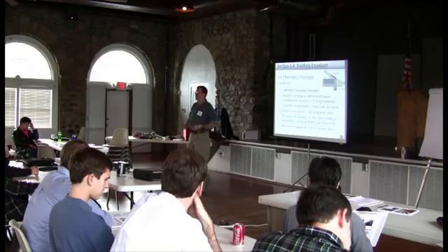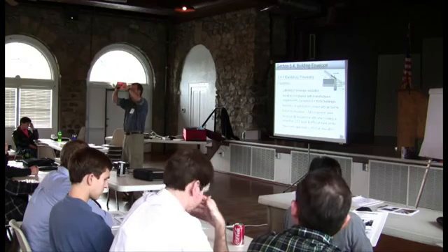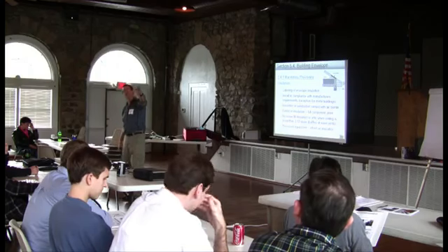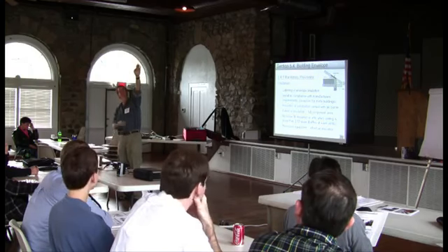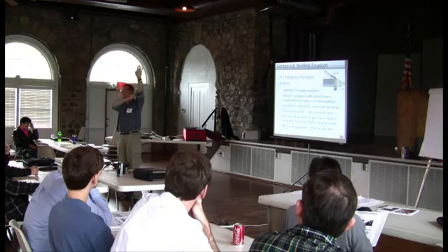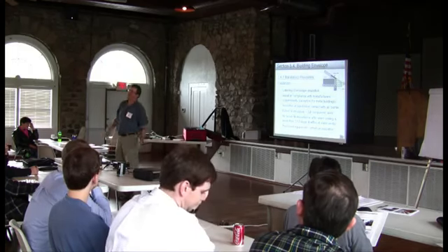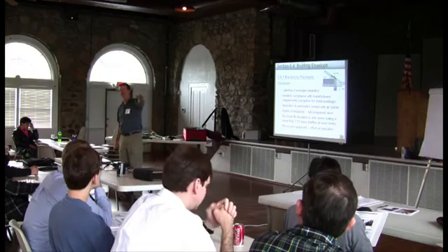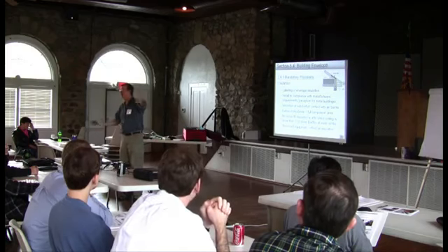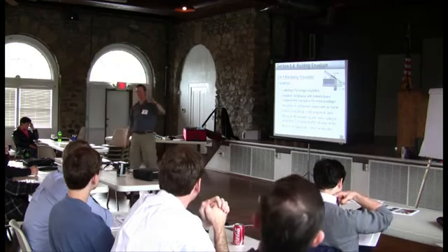Try to imagine someone has a scissor truss, okay, and there's an attic space up there, and let's say the truss is sloped like this in the inner chord here. Do you think that's a good candidate for blown insulation? What would happen if I tried to blow insulation right here? It would be kind of fun, right? So what they've said is you can only use loose fill if you're no more than a 3:12 slope. Kind of makes sense if you think about it. Otherwise, you're going to have to go to some other type of insulation.